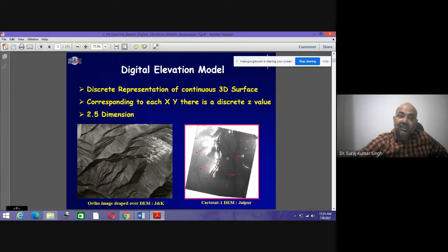So when in a digital elevation model you see bright white, that denotes a top or the peak, and when you go downwards, the dark blue or the dark black, in the form of drainages, you can see these are the lower elevation areas. So by seeing a digital elevation model you can identify the height, you can identify the slope. You can see on the left hand side the different kinds of slope, different kinds of drainage patterns. The drainages can be identified using a digital elevation model.